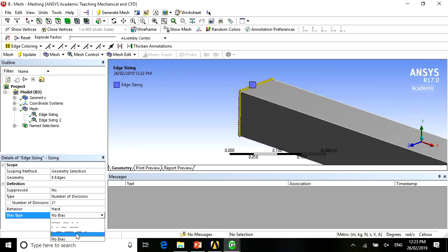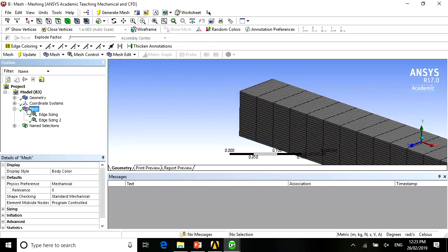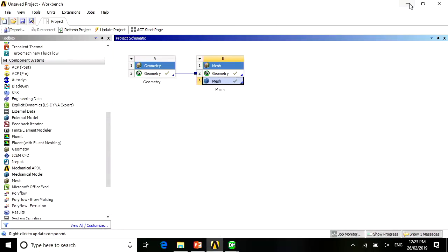Now, I'm happy with the mesh at the moment because I'm getting the resolution that is required, just for a demonstration. Okay? For more complex geometries, you may have to tinker around or may have to use some bias to look at your division. At this stage, it looks pretty good, right? So I'm going to minimize then. I'm going to solve the problem.